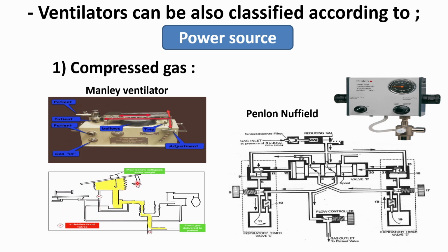When this needle stops, it will push this pillow downward, and it will push air in inspiration to the patient till the pressure here becomes equal to the pressure inside the patient, reaching equilibrium. It will stop inspiration and repeat giving the air, and the needle goes upward till it hits its limit, and again it will push air with this weight, with the force of gravity. Okay,